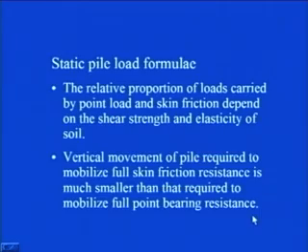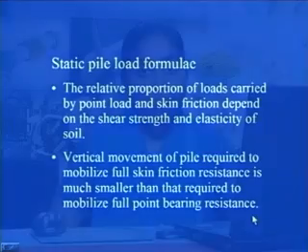So, you can see, as soon as the load is coming on the pile, first the friction is getting mobilized along the length. Obviously, when the load is coming, the pile is getting displaced. From that, the shear stresses are getting developed, and so they are resulting in frictional resistance. So, by the time your Q becomes equal to QF, that is at ultimate skin friction resistance, the deflection of the pile is not that much. To mobilize the full point bearing resistance of the pile, you need large vertical movement of the pile.